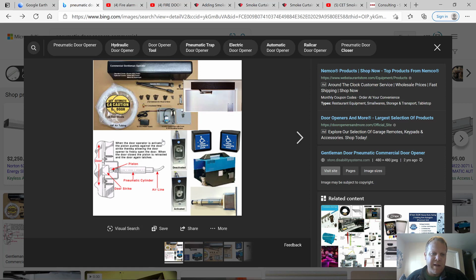And I think pneumatics is good in that, other than a control signal, it's not providing building power. You wouldn't have to run this from a generator, is what I'm trying to say. I don't think so if you had it on pneumatics, because pneumatic can be charged in advance, right? You could have a compressor with lines that are all charged, and all you need is a little activation from a solenoid to say open.